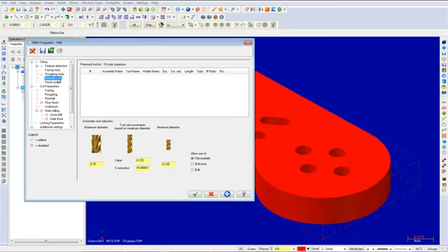This is where you set up the tools for a remachining operation. Make the following changes as shown. Once the parameters have been adjusted, select Finish Tools. This is where you set up the tools for the finish operations. Again, make the following changes as shown.